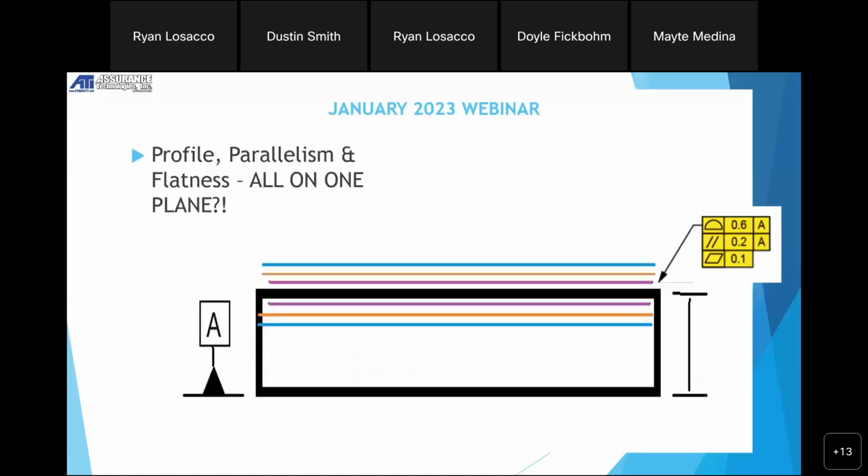If a lot of that made sense, awesome. If you have any more questions on that, feel free to shoot me an email. We can follow up and talk more about this. If you've never seen GD&T stacked on top of each other, you probably will on Monday morning now. You're welcome. GD&T might not be used a lot in your shop, but it's coming. The more these standards move on and get revised, we're moving toward less plus minus tolerancing and more GD&T tolerancing on these features to really control our manufacturing process and our qualification process.